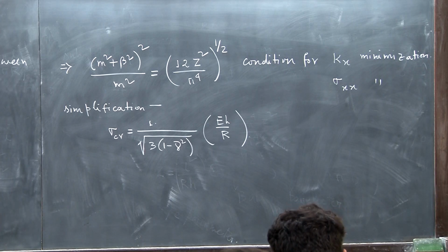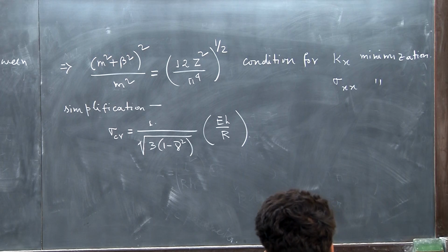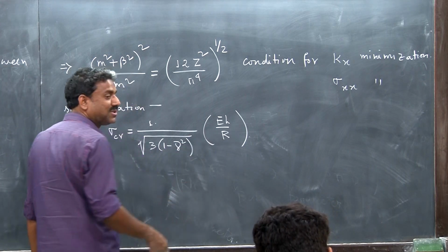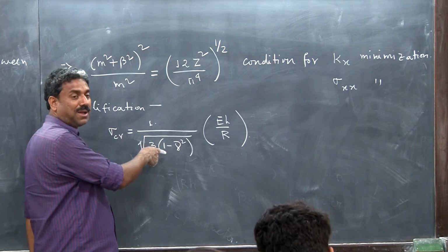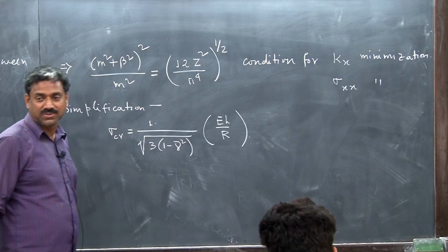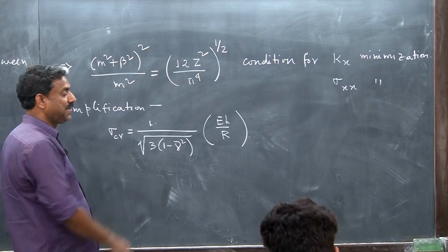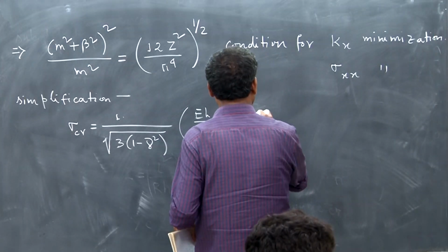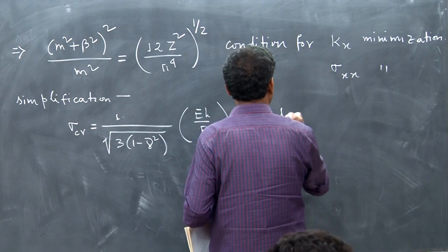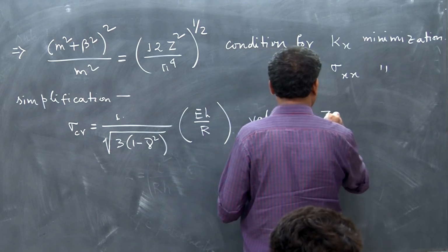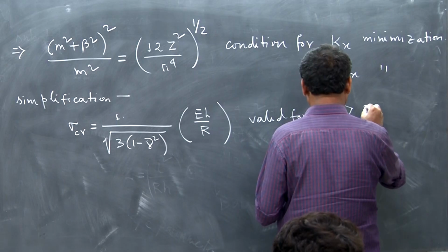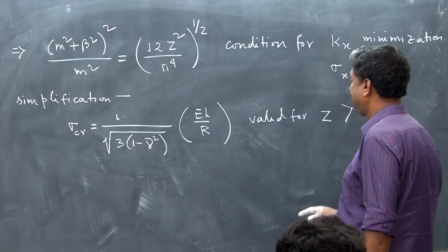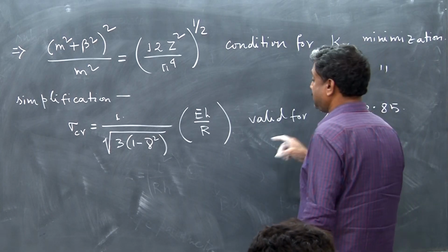When we assumed the one-way bending and axisymmetric, right? So that E H by R term was also there, but what was not there is basically this coupling term, including Poisson's ratio, right? This term was not there. Okay? So this is valid for Z, Batdorf parameter greater than 2.85, because the Batdorf parameter has to be positive. Okay, that I will show you why. This is important.